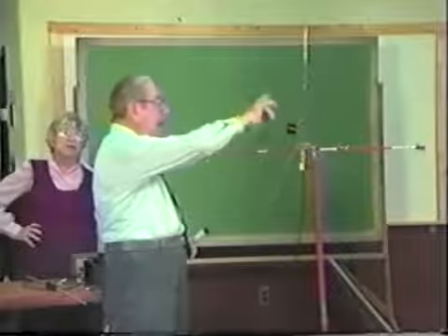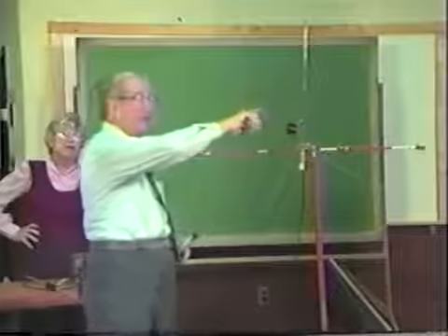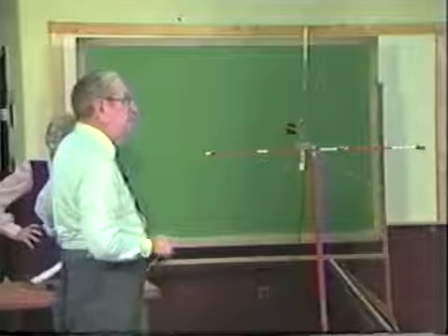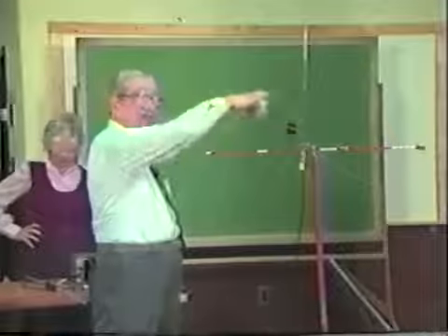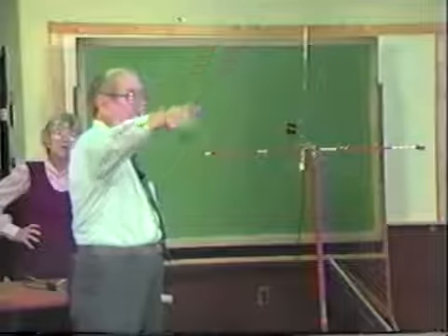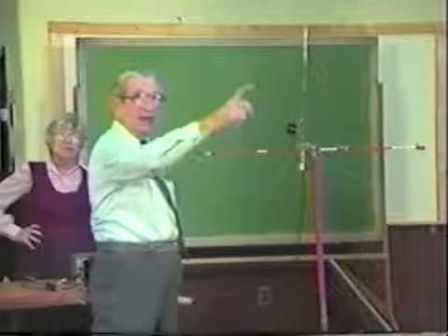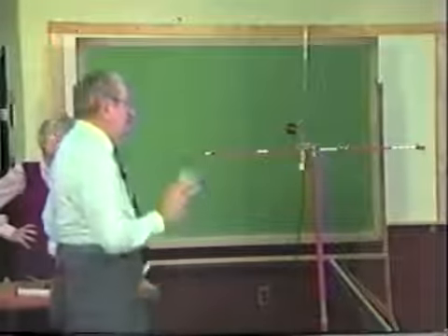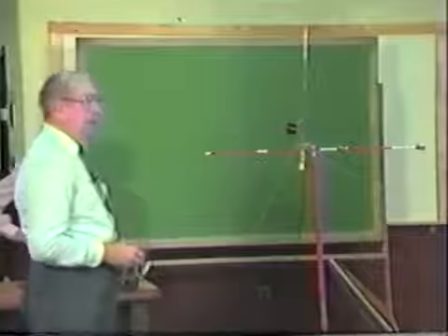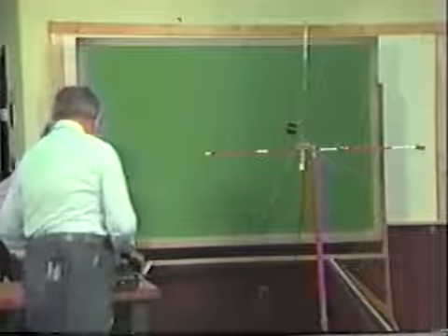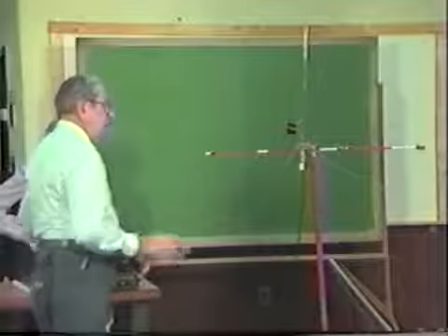not as a radiating portion of the antenna, but simply an image of the vertical itself, we now have a true quarter wave antenna that's radiating the same as the one I showed you on the car, the one on the mobile, where we have our donut all around this antenna and radiating out 360 degrees around it in a form of a low angle of radiation. Okay? I think that'll take care of the knowledge that we want to learn about vertical antennas. And we'll see if we can fill you in with some other information.